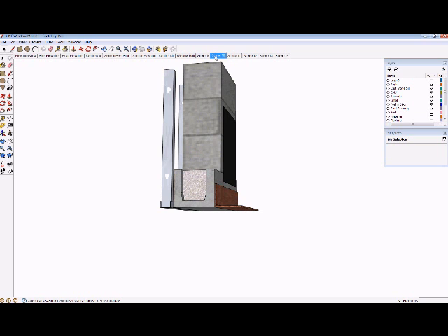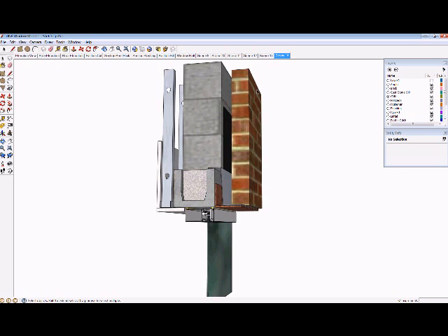So we'll put our peel and stick back on, then we'll put our flashing on, come back and put our window, fasten our window in place, seal our window with the manufacturer recommended sealants, and then come back and put the finishes in around it, the brick and also the drywall on the back side, and probably another beauty seal to the window. Now as you can see, this isn't an extremely complicated model, but it does allow us to hash out and work through some issues that may come up that are tough to see in 2 dimensions.